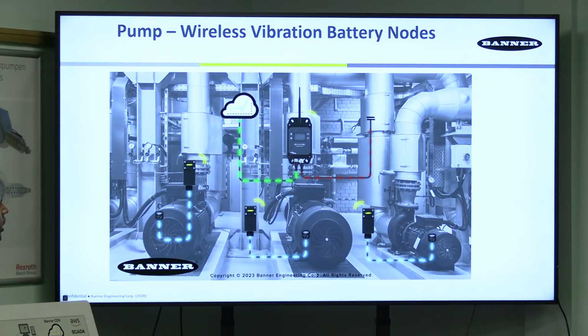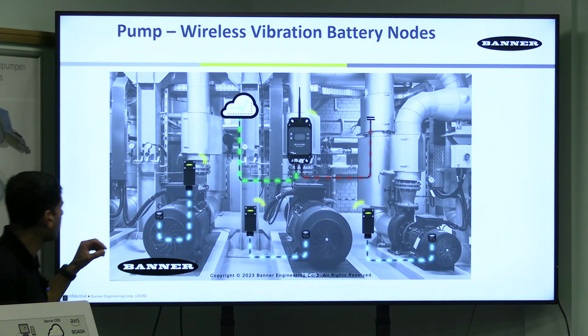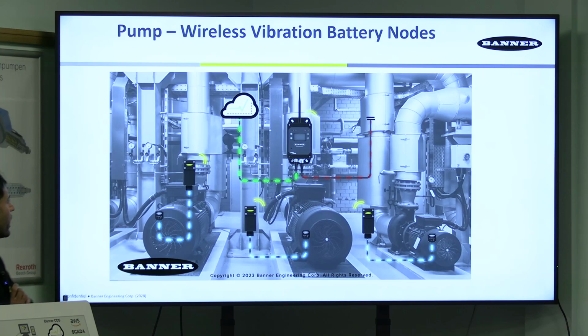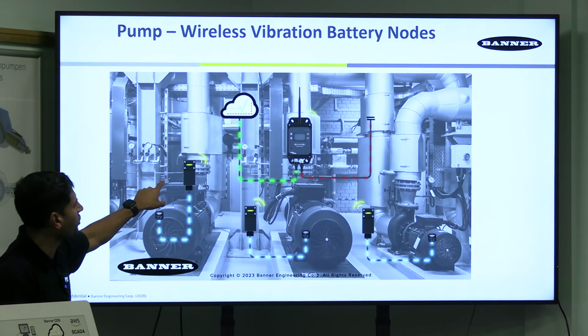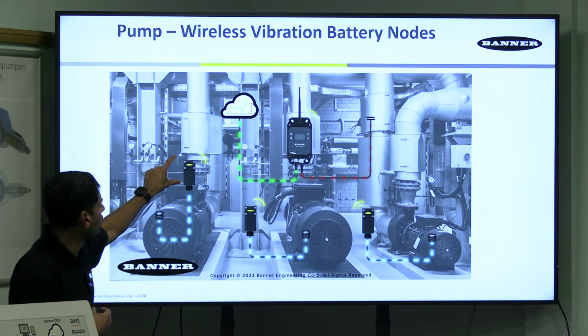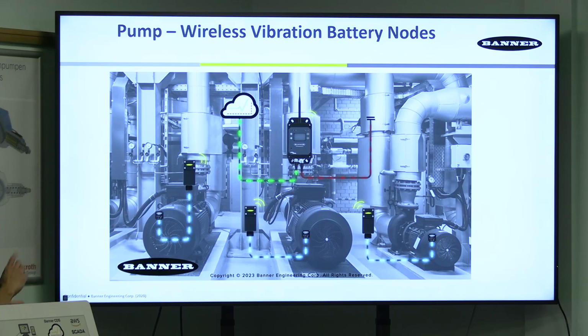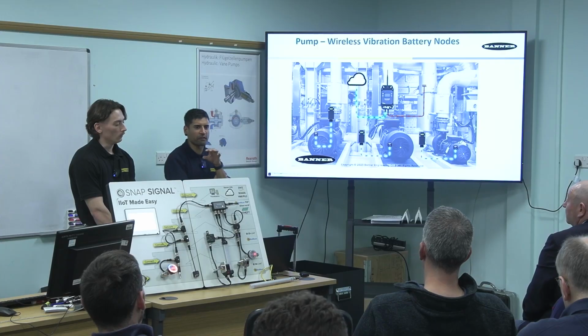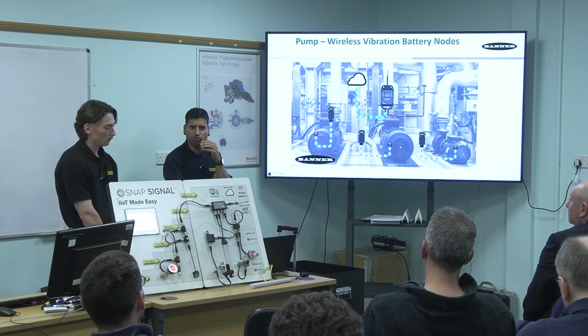And this is some of our wireless products as well. We have these vibration temperature nodes. They're battery operated, so you don't need any cabling. All we do is a simple triple click method. We can bind the node to the radio and send that signal back wirelessly. If we poll the device every 5 minutes on the 5th minute, we get optimum battery life.